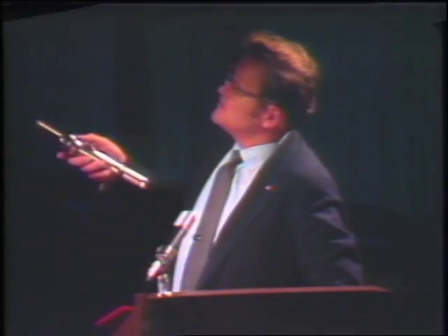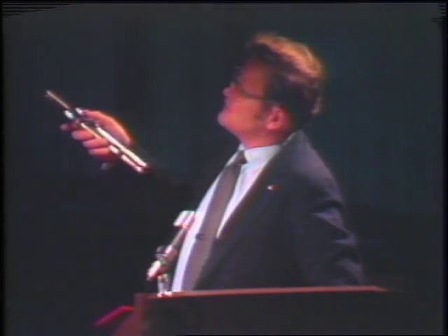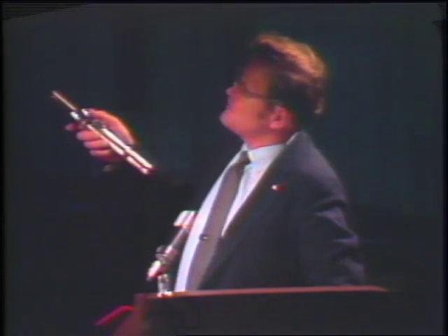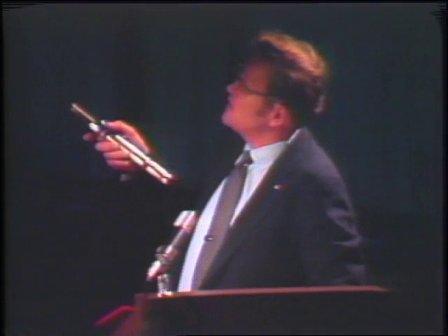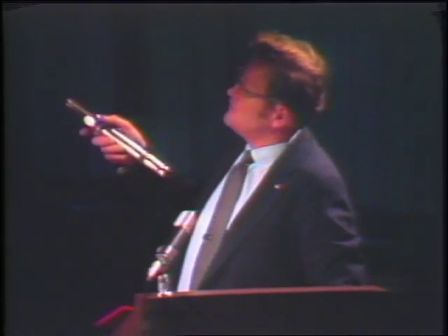Now, the instructions provided here, I doubt if many of you can see these either, but there were sequence changing instructions up at the top here. There's the memory cycle time shown here, and as a result of the sharing of those bits in the middle, you had to restrict some of these instructions to certain parts of the memory. So over here on the right defines what part of the memory those instructions are applicable. And the instructions marked with the asterisks required the extend operation to precede the actual sequence. Then these are arithmetic operations and then some input-output operations.